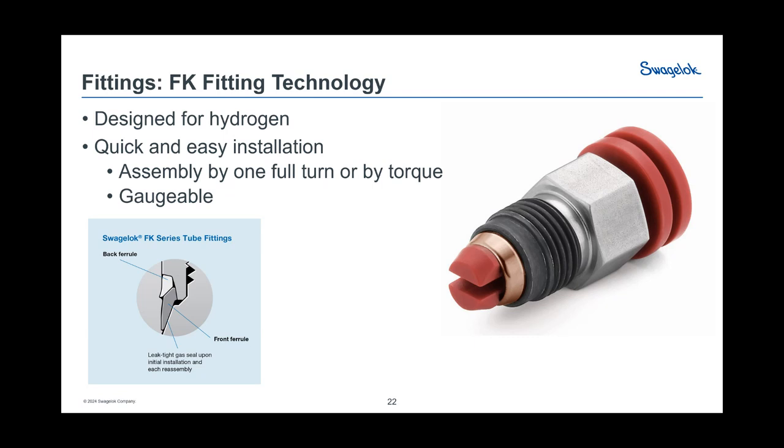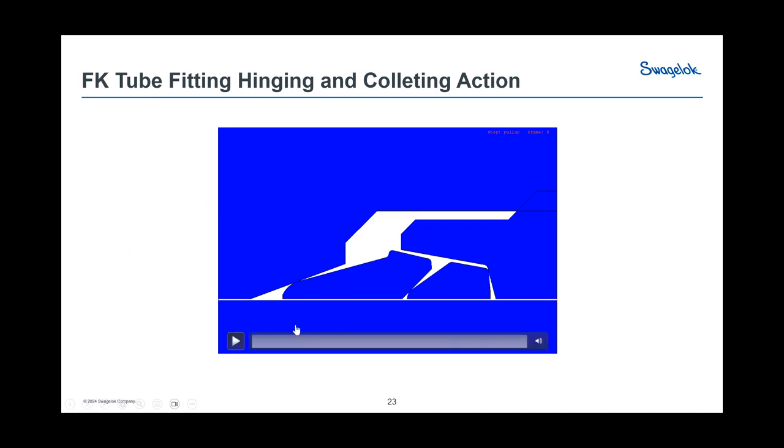The problem is other companies don't do that, so the installers are always worried that things aren't in the right place. Well, the problem is if you miss a back ferrule, or if you flip it upside down, or put them in the wrong order, then bad things happen, especially with high pressures and small molecule gas. So this way we were able to assure that it's always right when it gets out in the field. So lots of things done specifically for hydrogen, specifically looking at the potential of going into a potential automotive type factory. So I'll show you this. This is a model. This is again in that quarter symmetry I mentioned earlier. It's an FEA model, so finite element analysis done for how to develop this.